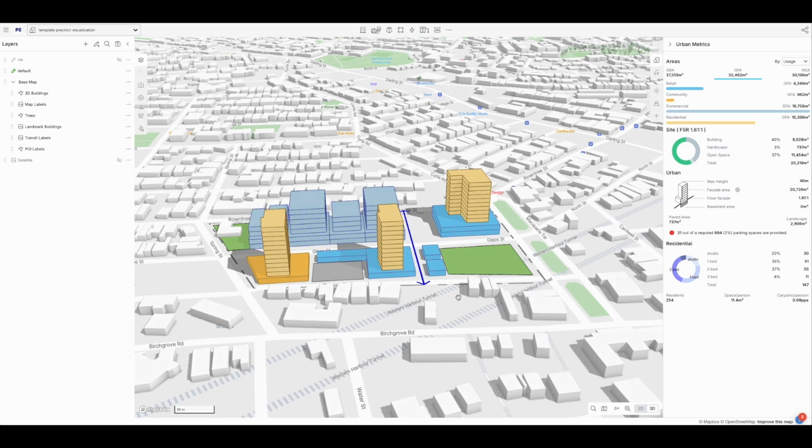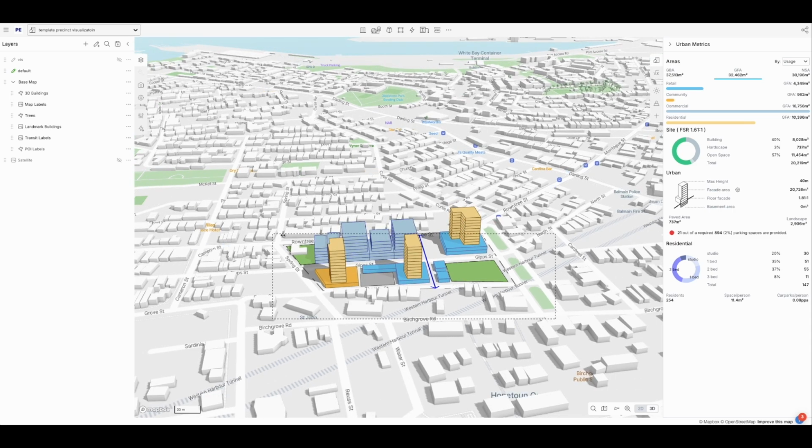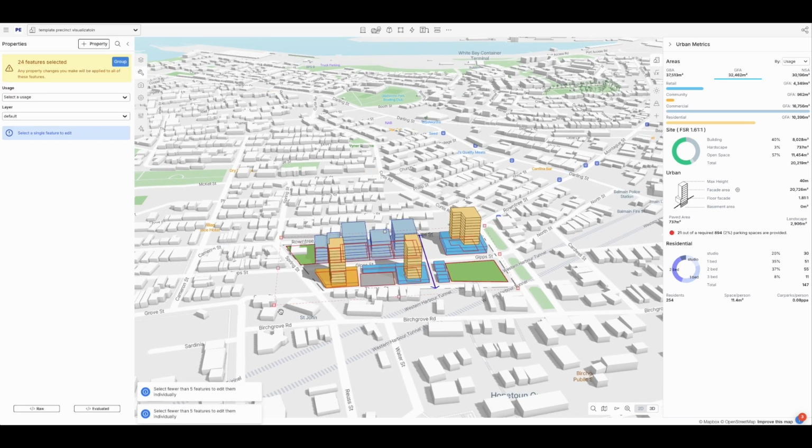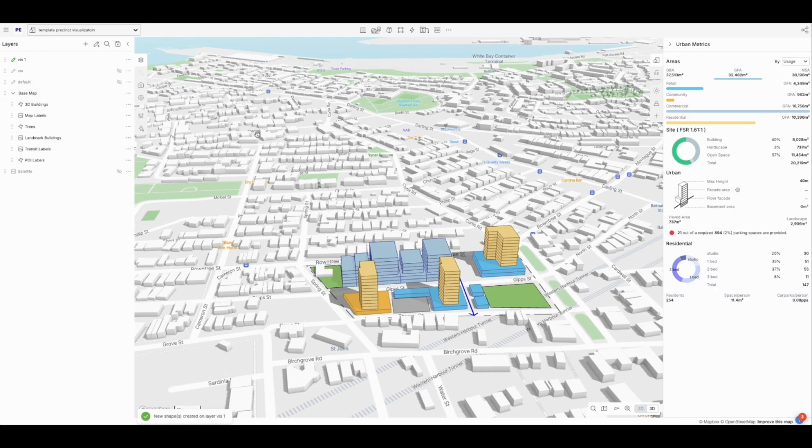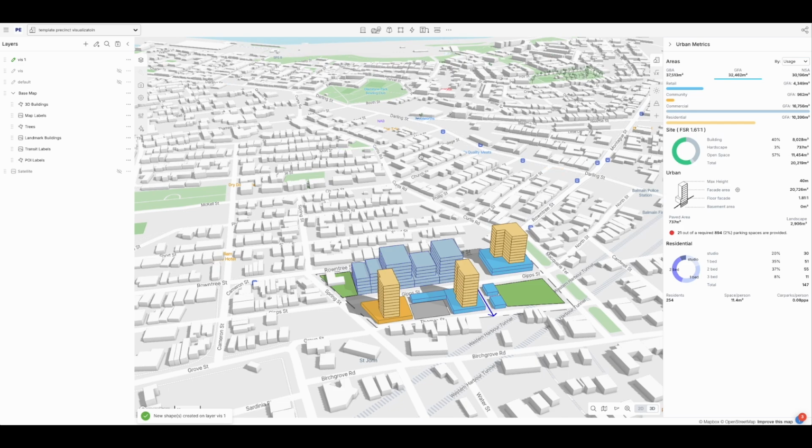So what I would do first is copy this in place, and create a new layer, and I'd call it Viz. I'll call it Vis1. And that's active. I'll turn this one off and paste that there on Vis1. Now the reason I'm doing that is because the areas are going to be pulled off the default layer, because we're going to probably muck about with it. When you're in visualization, you're solving a different problem set than simple reading of areas off of polygons.